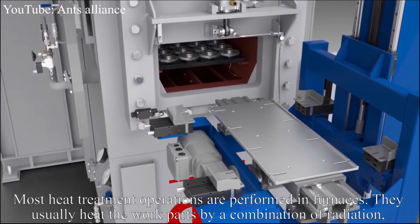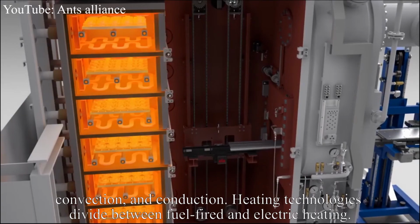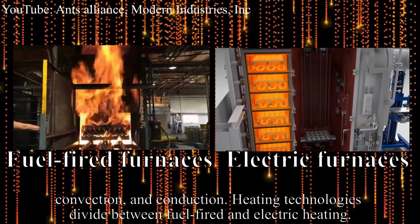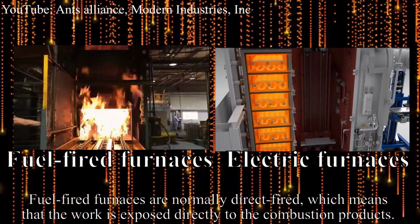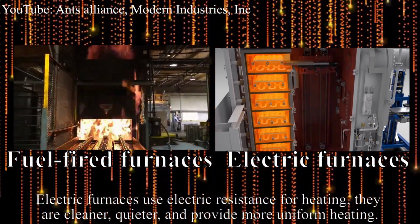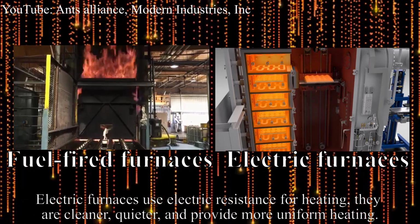Most heat treatment operations are performed in furnaces. They usually heat the work part by a combination of radiation, convection, and conduction. Heating technology divides between fuel fire and electric heating. Fuel fire furnaces are normally direct fire, which means that the work is exposed directly to the combustion products. Electric furnaces use electric resistance for heating. They are cleaner, quieter, and provide more uniform heating.